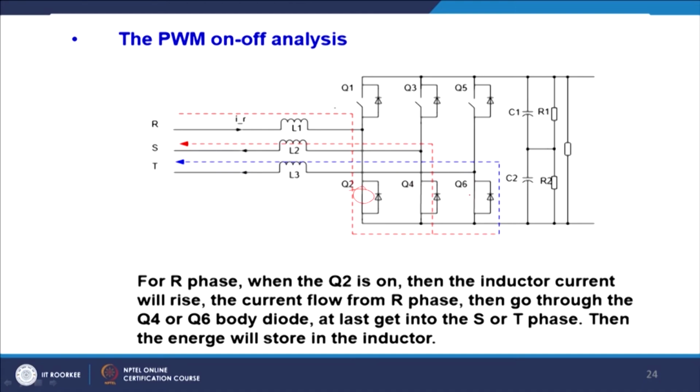So, this is essentially the state 0 0 0 in space vector modulation. In that case this gives you the boost mode of operation. You can see that depending on the direction of the current, because IA plus IB plus IC should be equal to 0, assuming IA enters, it will go back through the diodes D4 and D6.